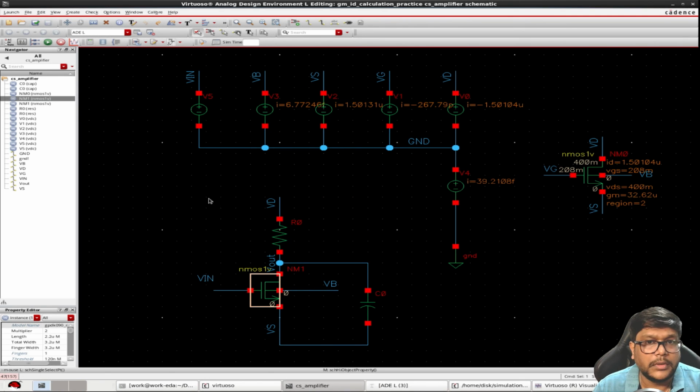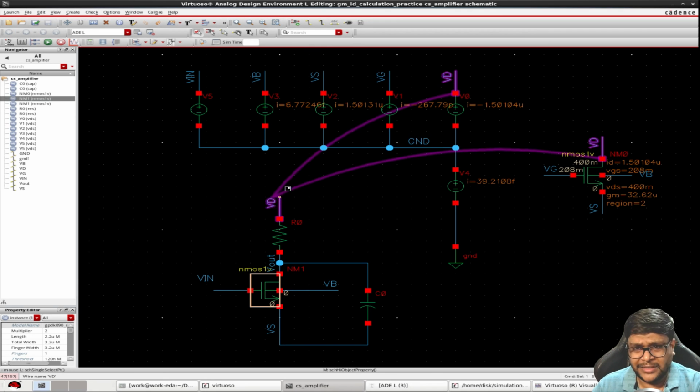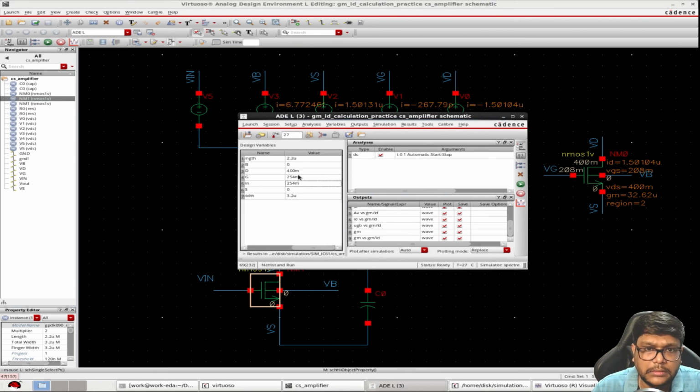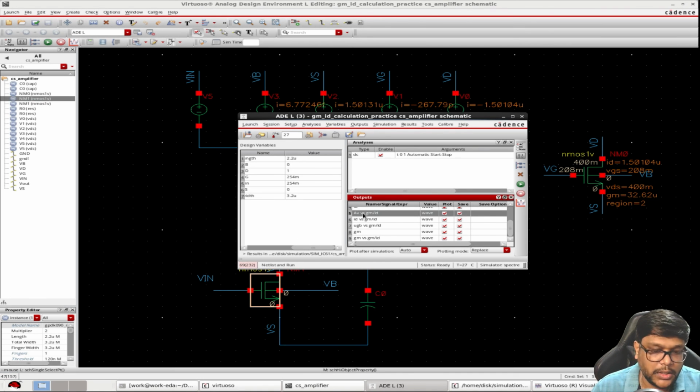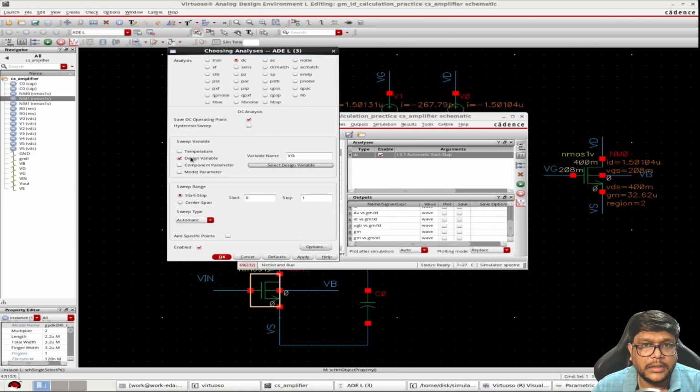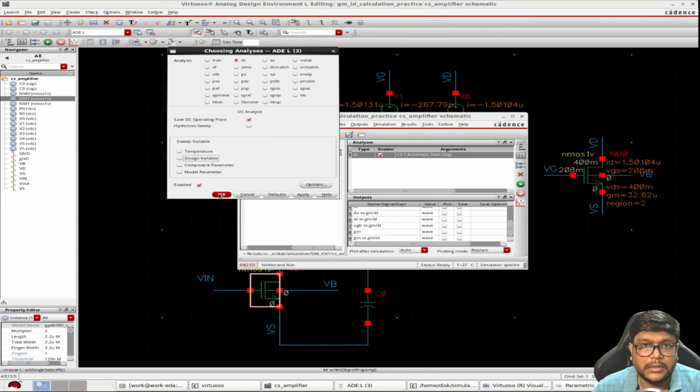So now this is our VD, so I'll change this VD because I have already calculated for our NMOS. So now this VD or VDD will be 1 volt. So I'm changing this one to 1 volt, and I don't need these calculations for now. Double plot, and I don't need this one. Apply.